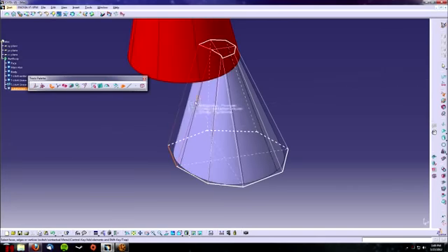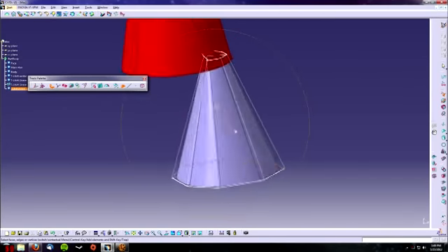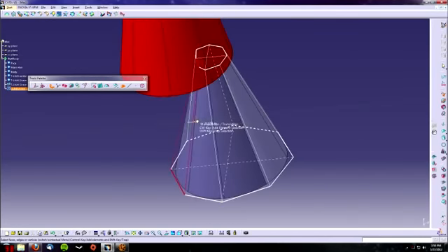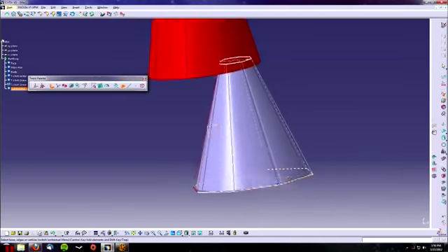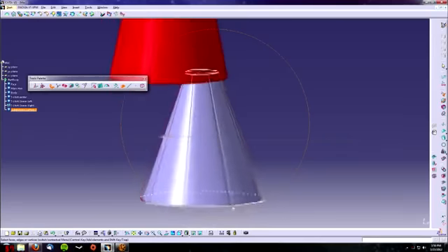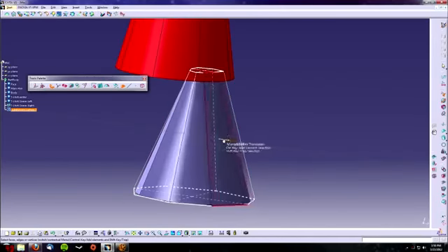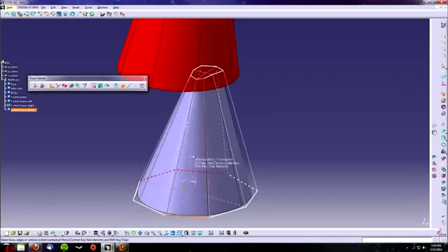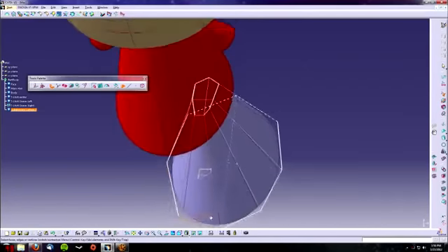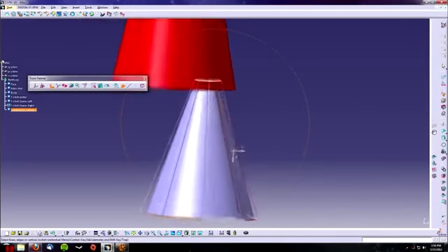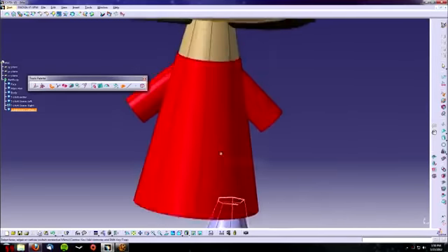Also, to make sure his legs more closely resemble his actual character look, click on the surface, and then use the translation. You can manipulate separate surfaces by themselves to create what his pant leg looks like from his front or left or right side view. You can also use the select by edge, which is the next icon over from the little surface, or by point, where you select different points and move those individually around, or select multiple ones and use the control and click command. This takes a little bit of time, so be sure to reference your pictures and design close to how his pant legs would work.